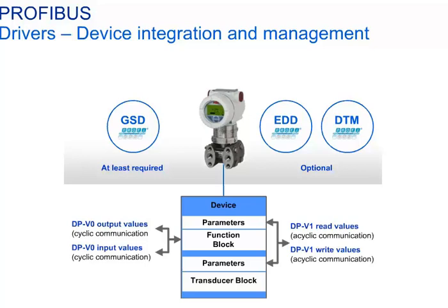Optionally, and only for acyclic communication, EDD or DTM drivers can be used. They allow to read parameter values from or write them to field devices. These drivers are mainly used in the commissioning phase and for service purposes.